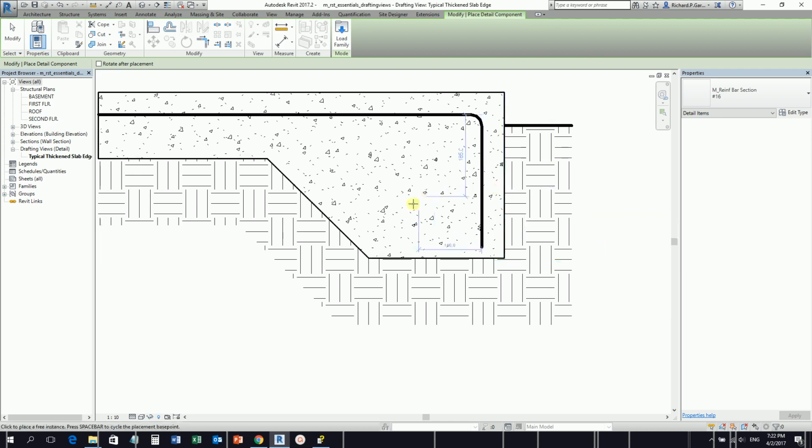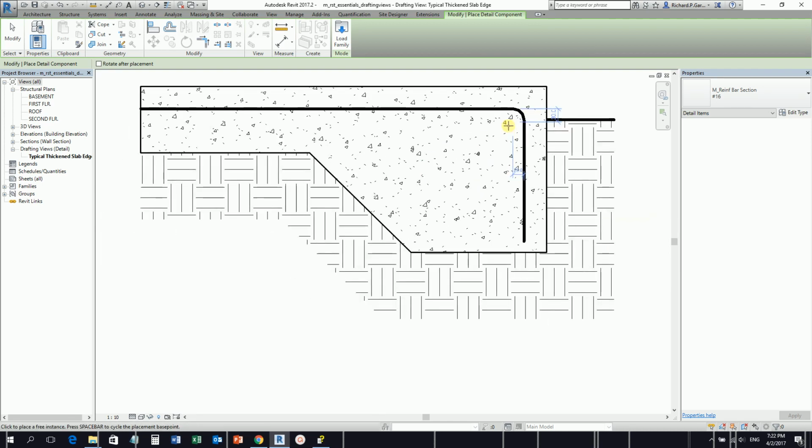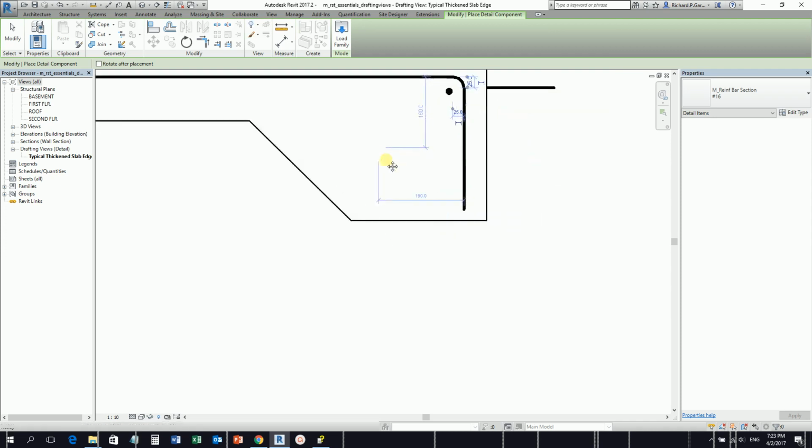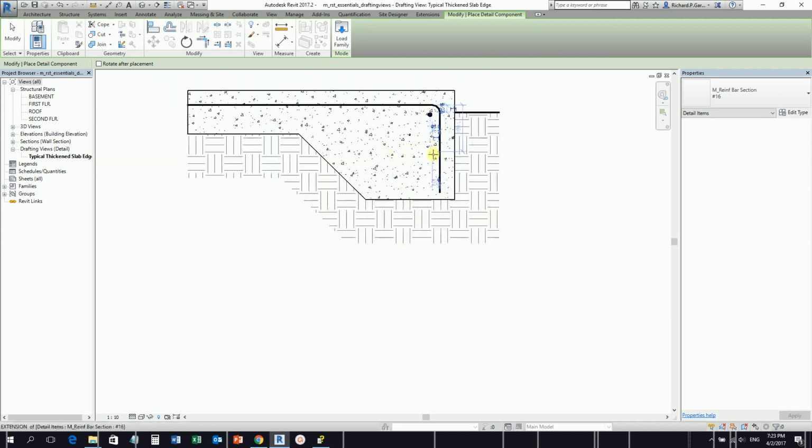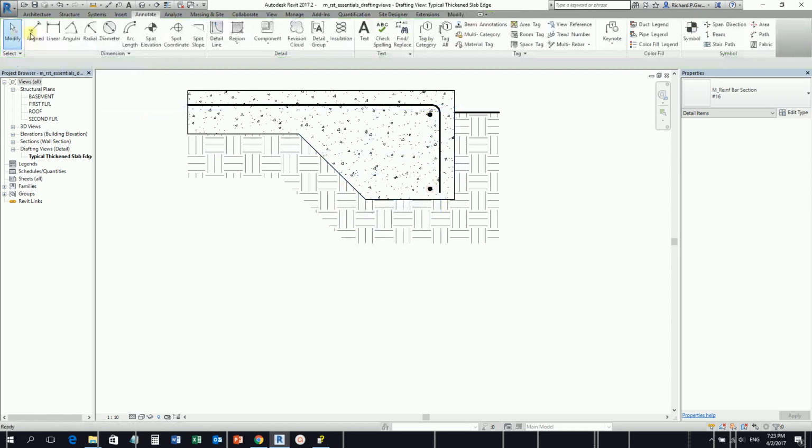Now I'm going to click the corner here of the wide lines representing the bent bar to place the reinforcement bar. So this is my bent bar, and then I'm going to place the reinforcement bar. Let's say I'm going to place it here. Okay, all right, there you go. And then I'm going to place another one here below. There you go. And then I select modify.